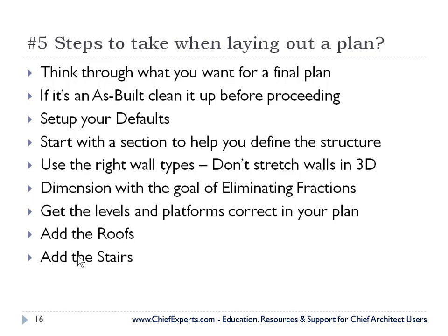If you do these things: get your dimensioning right, draw your plan, get your levels and platforms correct in your plan, add your roofs, add your stairs. You get past these things, the rest of the plan is usually pretty easy. But again, once you get more proficient with Chief and you understand what some of these things are doing, then it's not so hard. And then you can add the rest of the detail: cabinets, doors, windows, things like that. But again, be careful as you're putting things in. All right, so dimensioning is important.